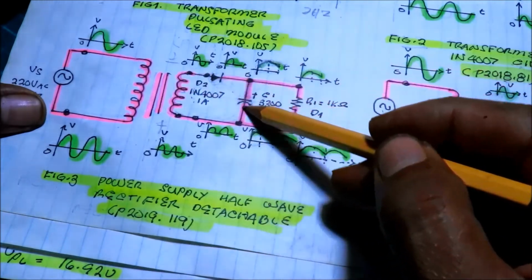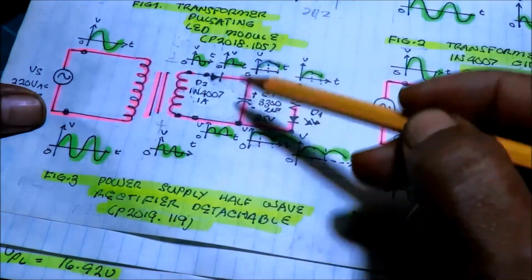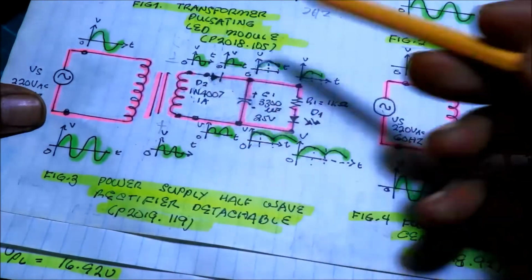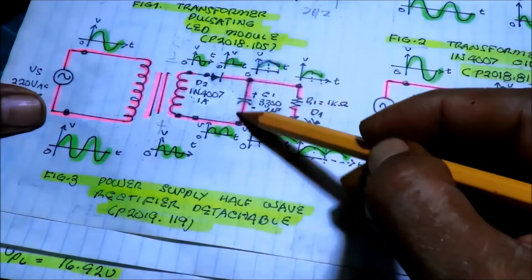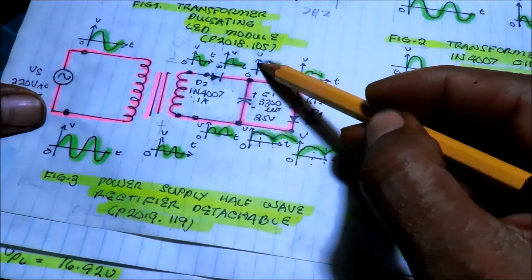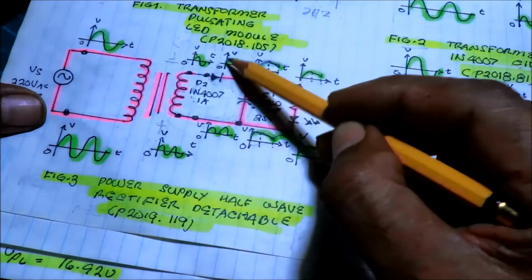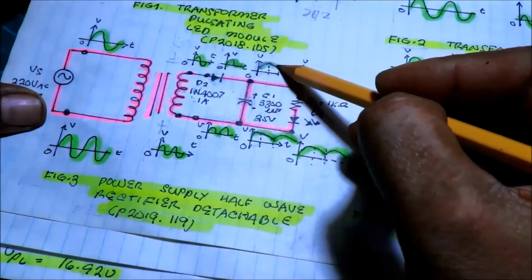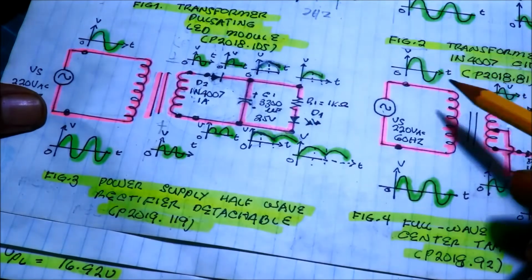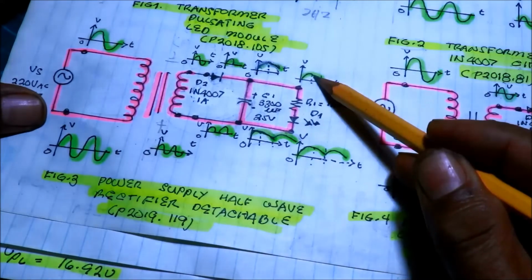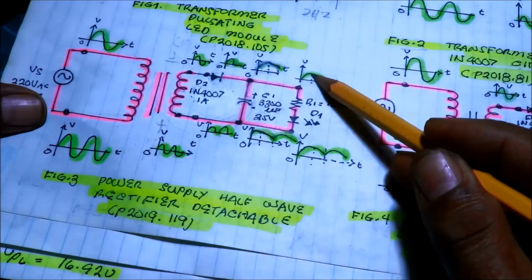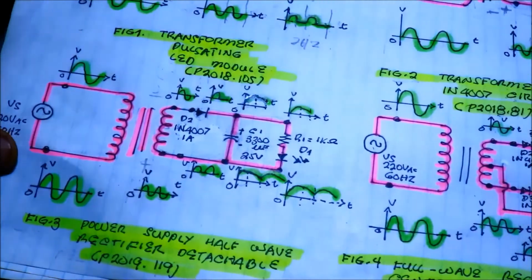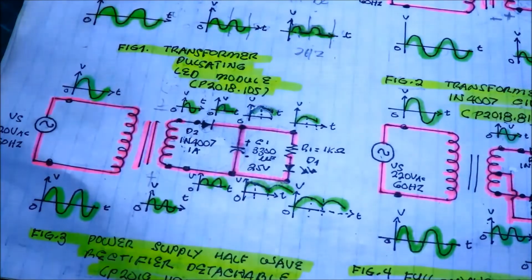During the half cycle, still the same. It conducts. The other half cycle, it will not conduct. The difference is we're introducing a capacitor that filters the waveform. Instead of just like this, it becomes like this. See? Okay, we have another circuit.